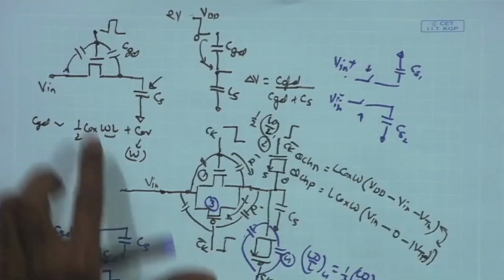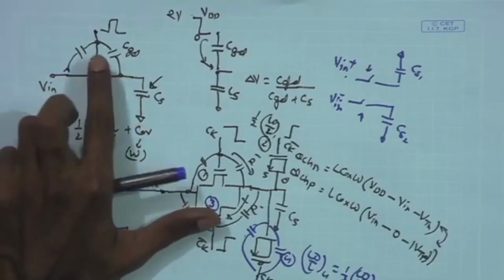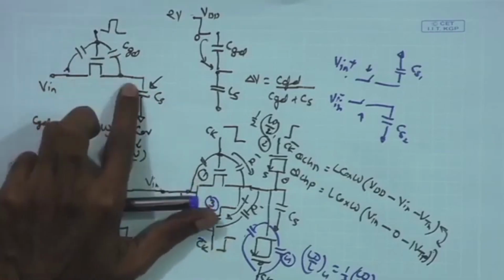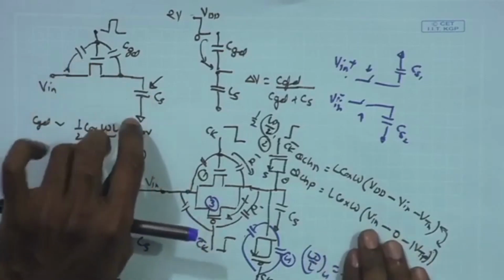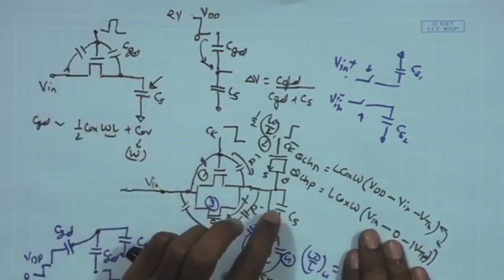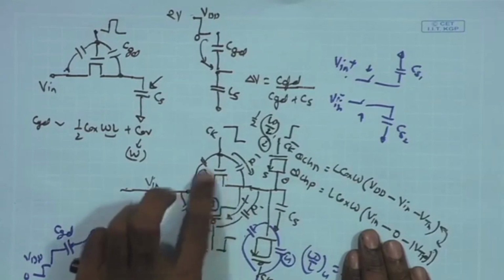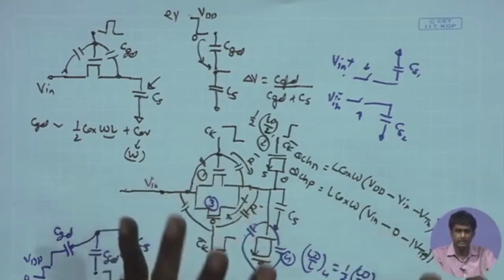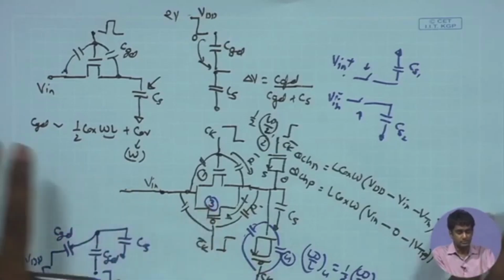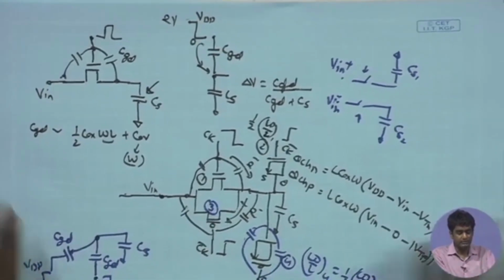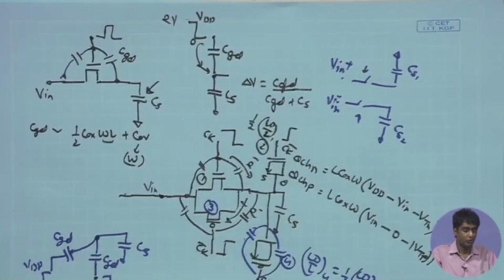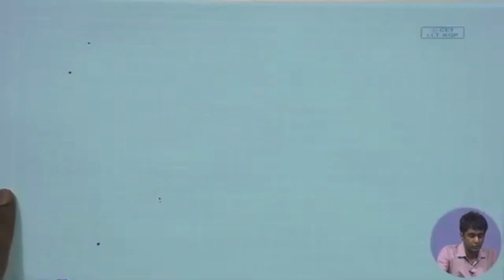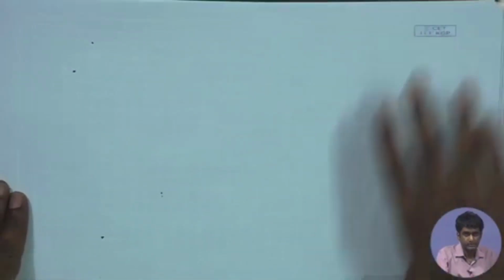And then we also tried to look into other non-idealities like the parasitic capacitance resulting in clock feed through and the channel charge injection, which can lead to inaccuracies. And there also we confirmed that a large ratio of CS versus the parasitic capacitances of this MOSFET can be helpful in mitigating these non-idealities. So now once we have considered this sample and hold unit, we can go further and look into other fundamental building blocks of our